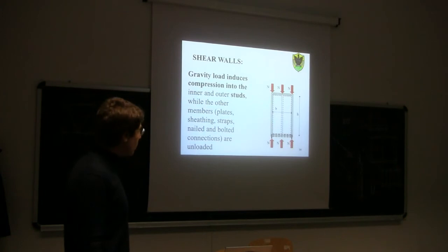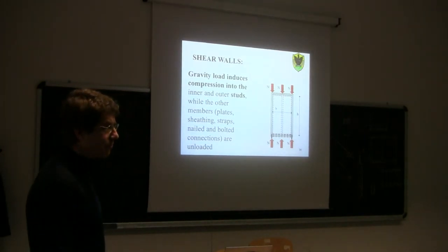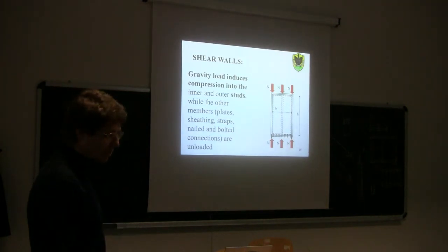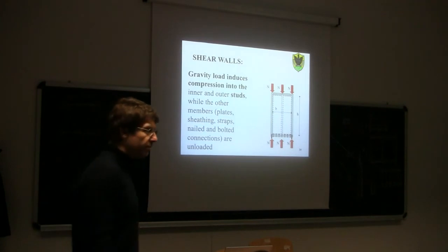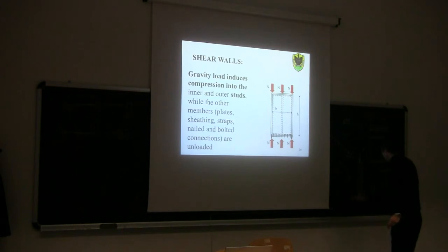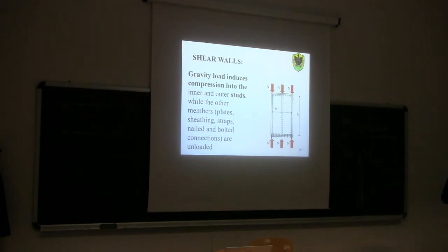Okay. What about the bolts here in the hold down straps? Are they loaded under gravity load? Again, think about the load path followed by the forces to get to the foundation. So here's the foundation. Here these hold down straps. Do you expect most of this load to go down here, or just to go through direct contact from the plate to the foundation?